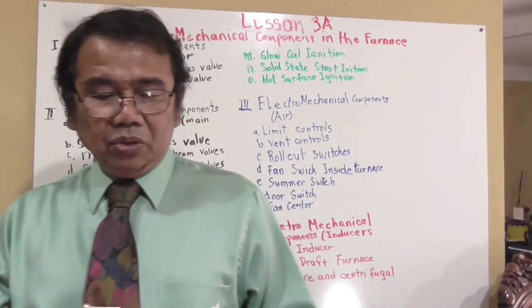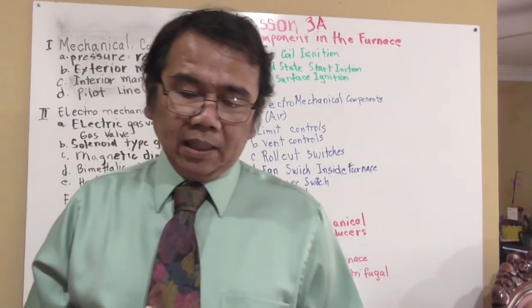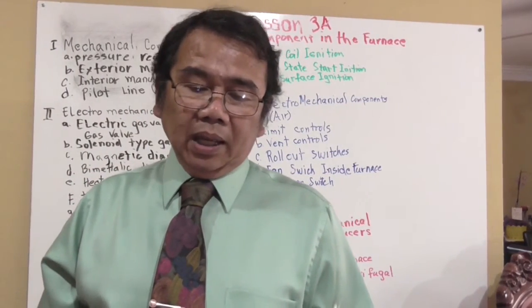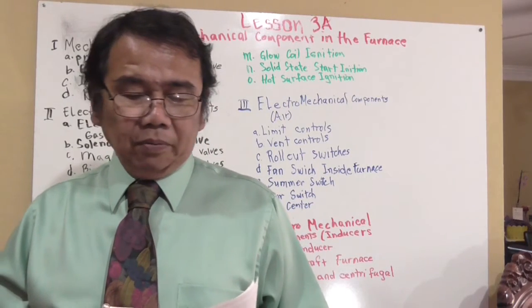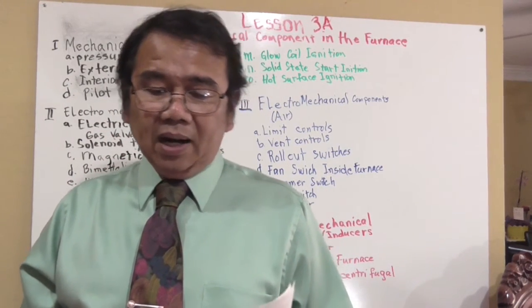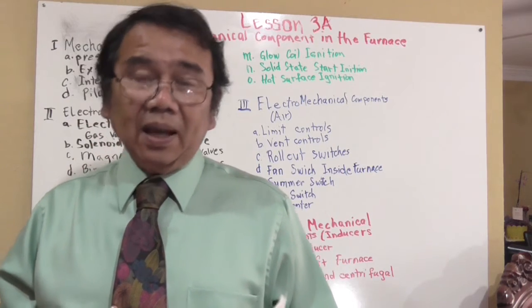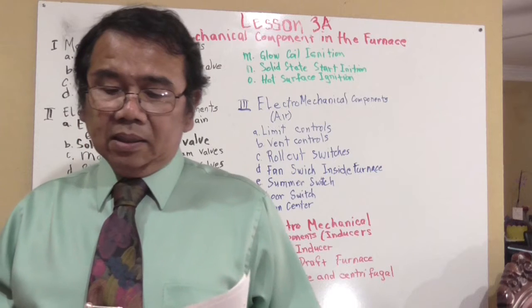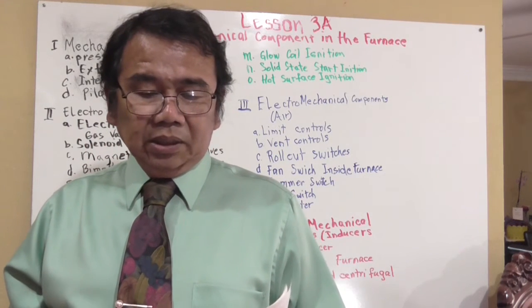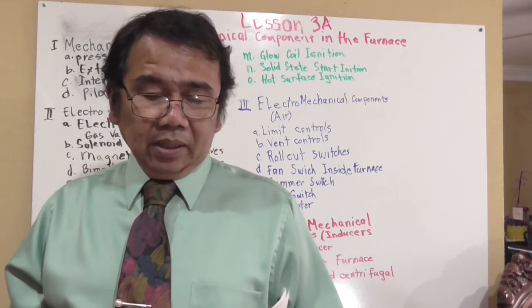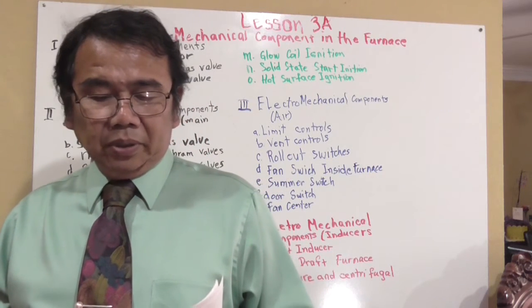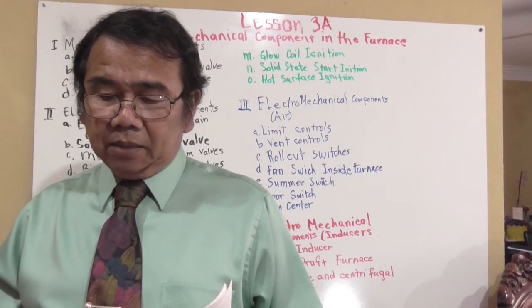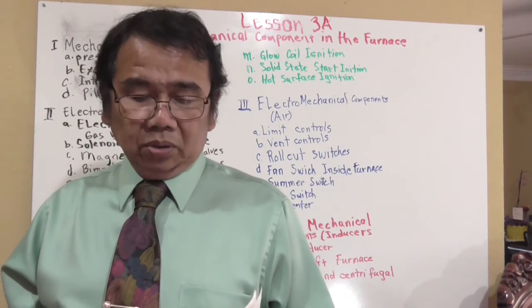If the equipment is using a centrifugal switch, the inducer motor will have 4 wires coming from it. 2 of the wires are the 115 volt power supply. The other 2 are leads that are connected to the centrifugal switch. When an inducer motor with a centrifugal switch reaches 90% of full speed, the centrifugal switch will close.